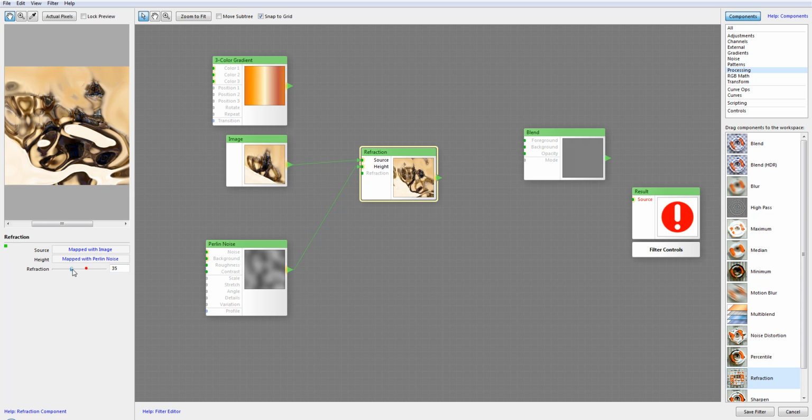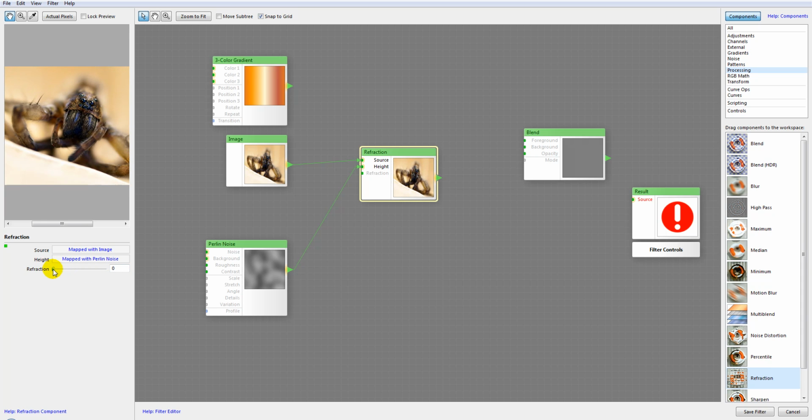However, refraction is set to 60, and you can obviously change and modify it. However, this refraction is mapped from 0 to 100, so it's not truly representative. For example, if you're using glass, the refraction will be 1.33 by default, but when you work with this slider, the adjustment will be a little different because it's going from 0 to 100.